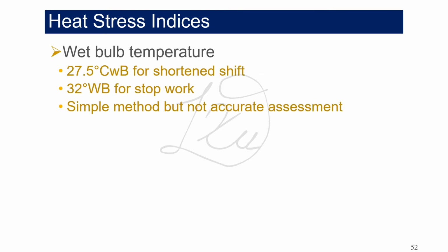The wet bulb temperature of the ambient air is the most powerful variable affecting body cooling. Some mines retain the wet bulb temperature as a sole indicator of climate acceptability. A wet bulb temperature of 27 to 28 degrees may be employed as an approximate criterion above which work rate or shift hours should be reduced. In former years, 32 degrees has been regarded as an upper limit of acceptability for very hot mines.